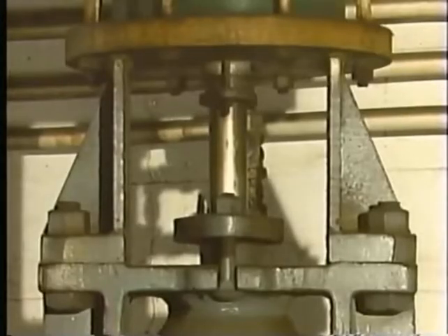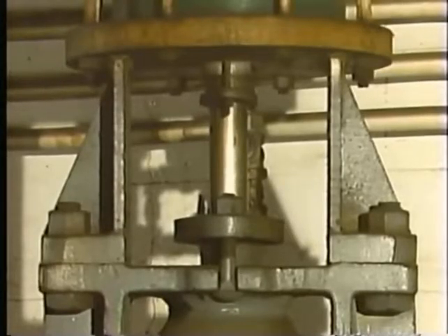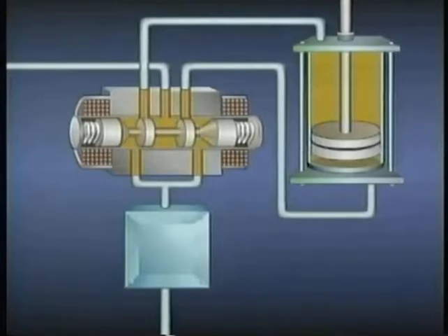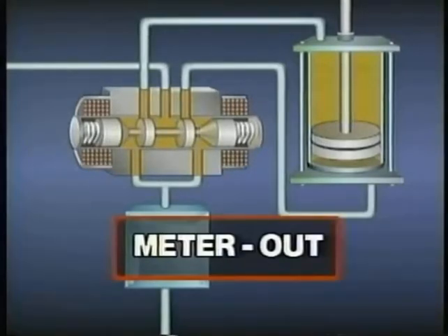The valve can be opened and closed gradually and smoothly, but it doesn't exert enough force on the actuator to run away. In situations where runaway may be a problem, a different method, like meter out, is typically used.